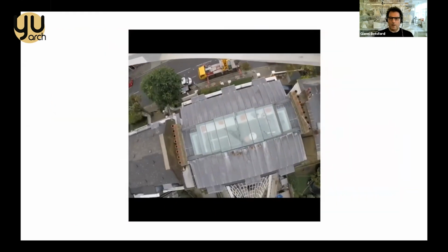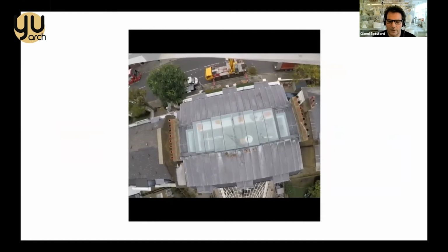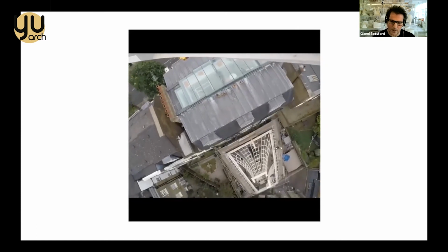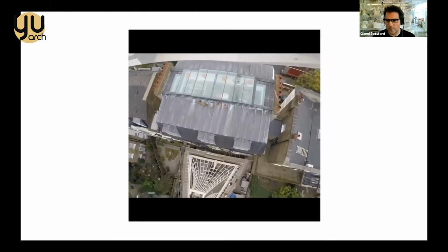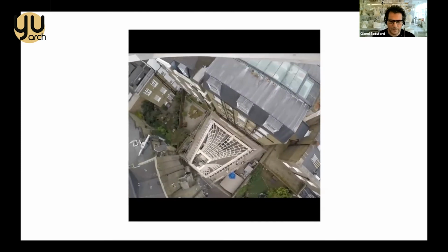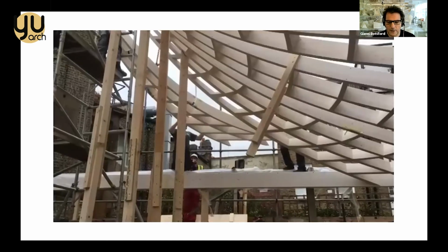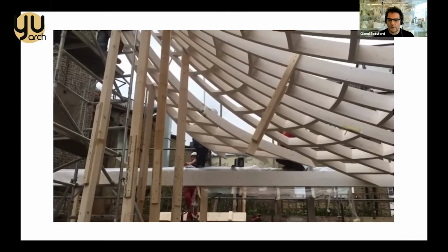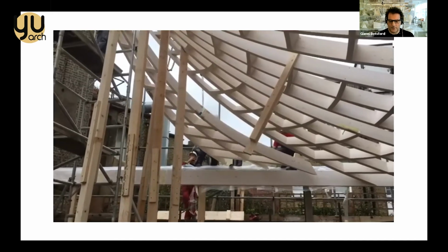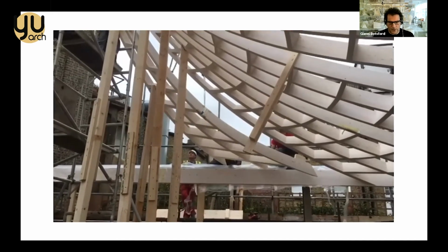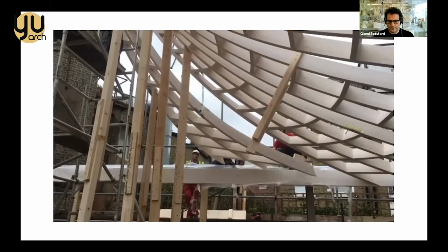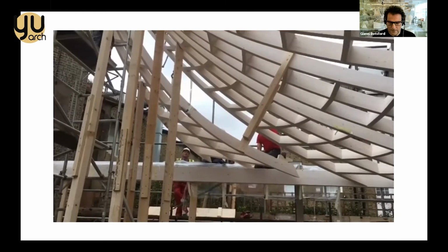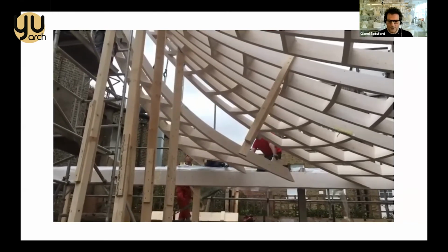And then these parts were delivered to site and craned in. I think there's 12 different sections that were prefabricated and lowered onto the site, which was meant as a very quick operation on site itself. You can see one of the sections being lowered. So the radial beams connect these elements. They leave out every third one, they leave out the radial element, and that gets fixed later. And the 12 sections are lowered in and propped up temporarily, and then fixed once everything is connected together. And there's a satisfying moment in a second where it actually just fits properly.